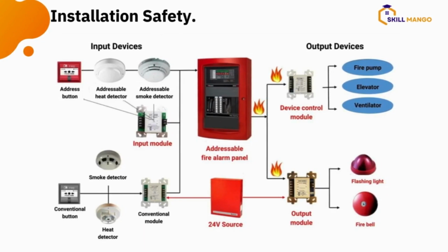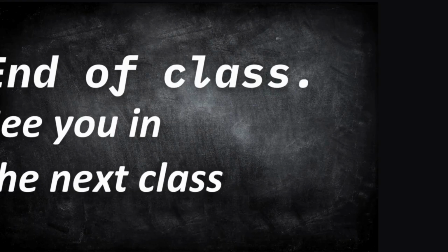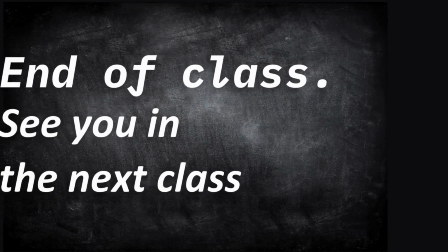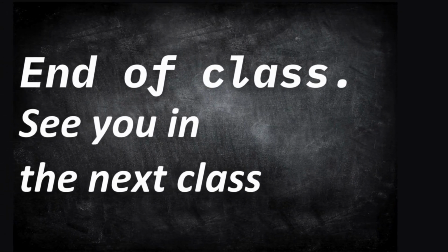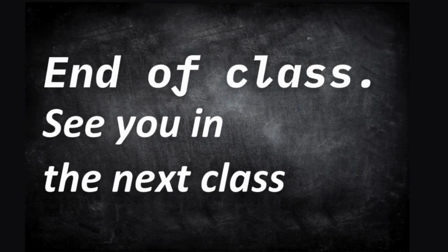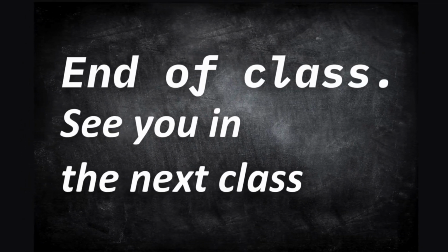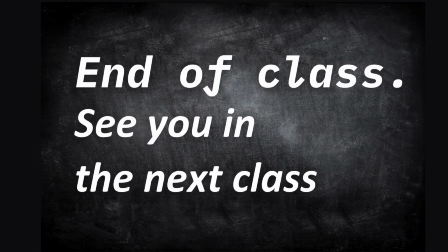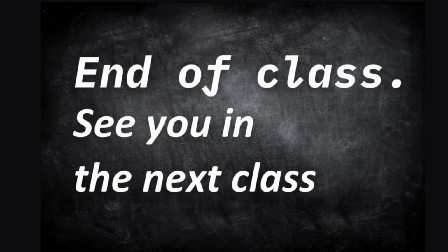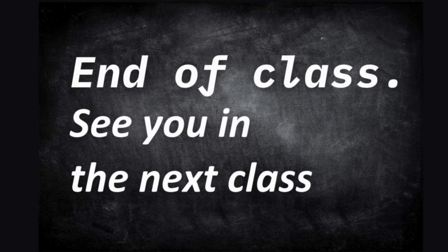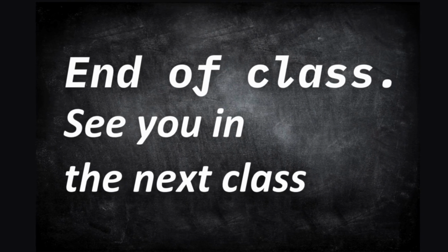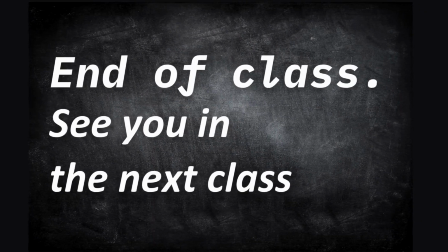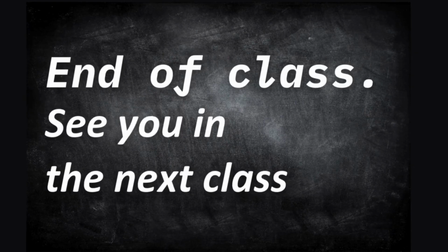Safety first, extremely important. So this is a very brief class about safety when you're installing. In summary again, ensure that you use original cable and you do power isolation. Remove electricity, don't connect it yet until everything is well set up and ready to be tested. Then let the two 12 volt batteries be well placed inside the panel. Then you do your connection before you power up, so the battery can be fully charged before you hand over and commission the site.